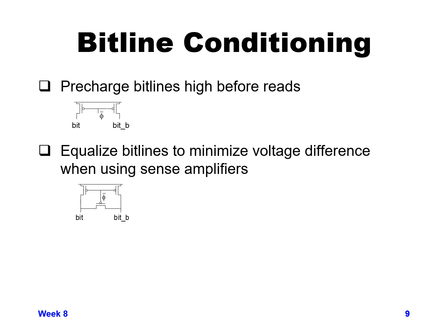In addition to that, typically we'll also have an equalize PMOS transistor tied between the two bit lines. That's because when one bit line was pulled low during, let's say, a read or a write, when we go back to pre-charge, the bit line that was already high, since it's fully high, might wind up being all the way at VDD, whereas the other one, during the time that we have to pre-charge, we might only get up to, let's say, 98% of VDD.